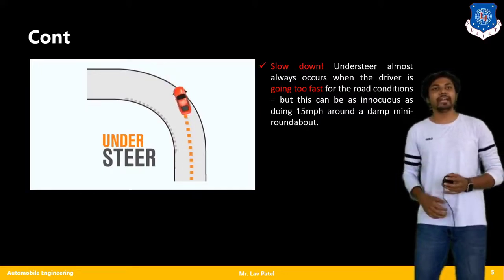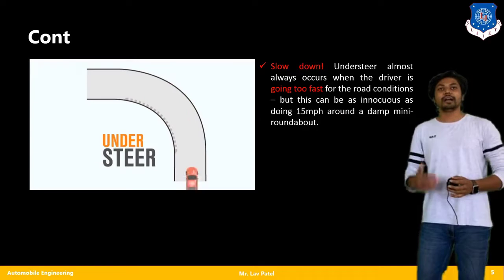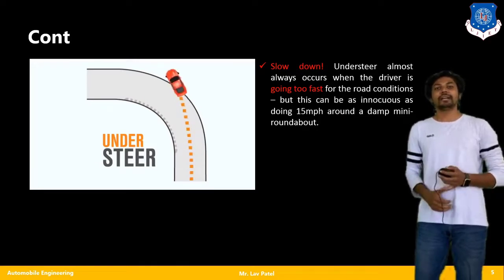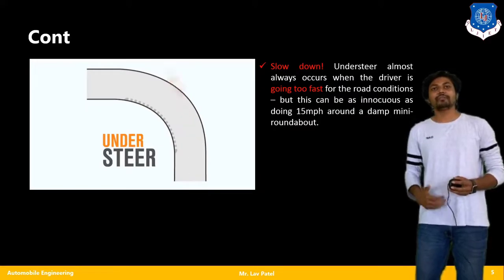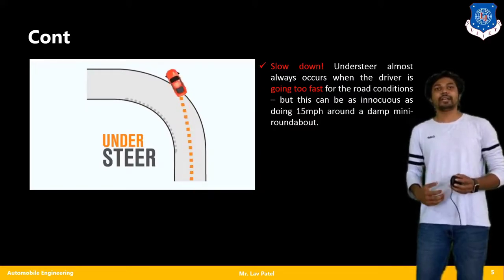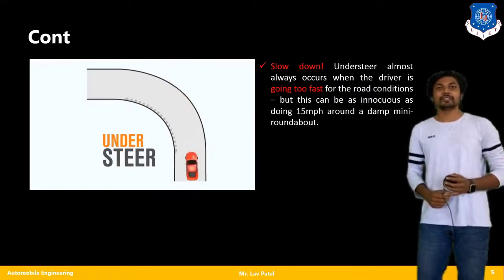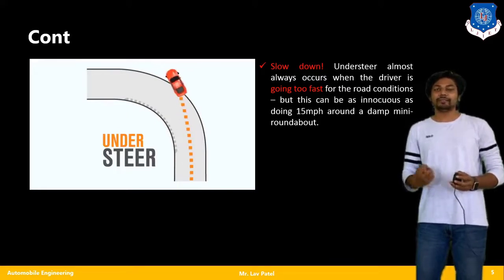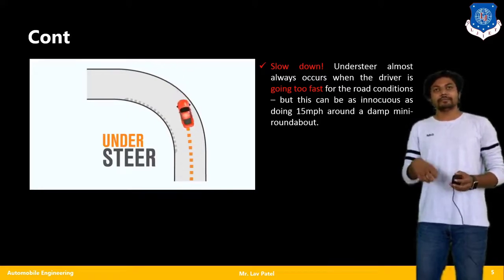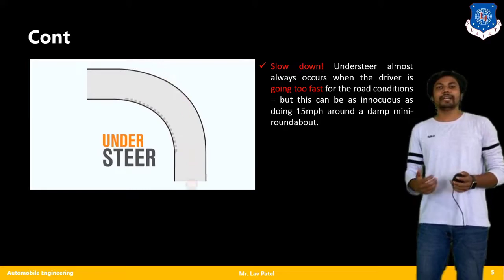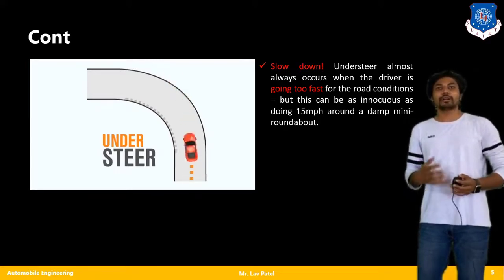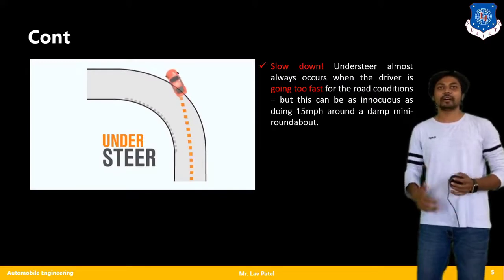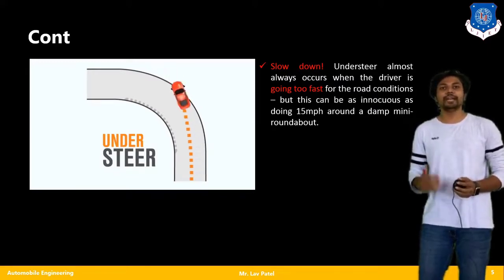Sudden braking and sudden acceleration are again not going to help with the understeer effect. If I have to accelerate or brake in an understeer situation, I need to apply force very softly or increase it gradually, in such a manner that it does not lock my front wheels, so that slippage does not happen.